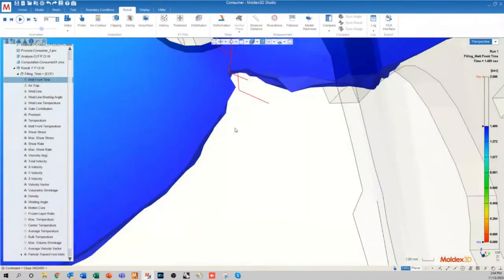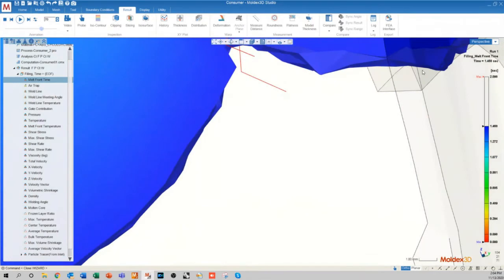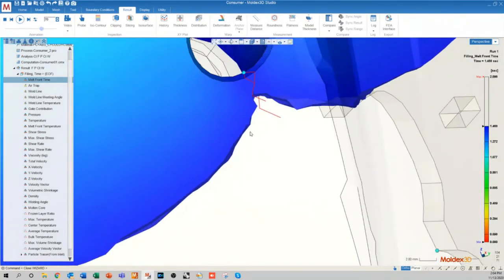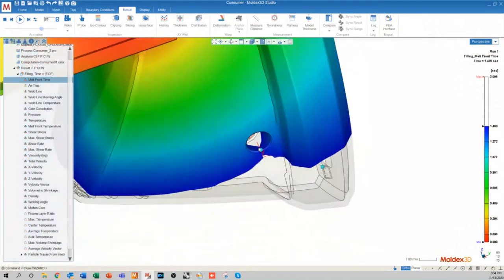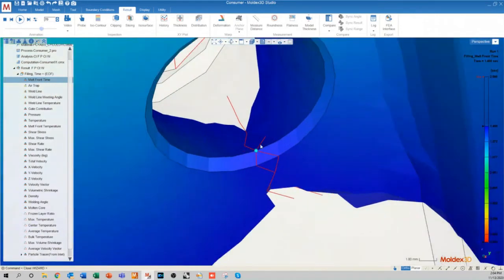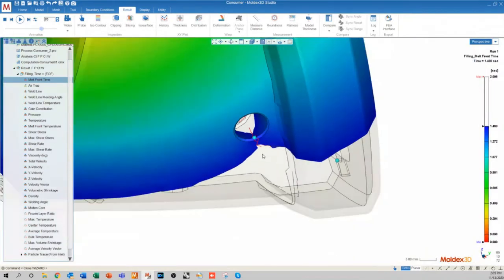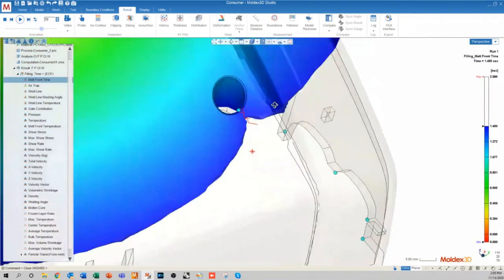After that, however, you can see this angle here, maybe like 90 degrees, something like that. It actually opens up pretty quickly, which is a good thing. But right at this feature, if I were to apply any sort of external force, I would be really worried that my part would fail there because it has such a low weld line meeting angle.